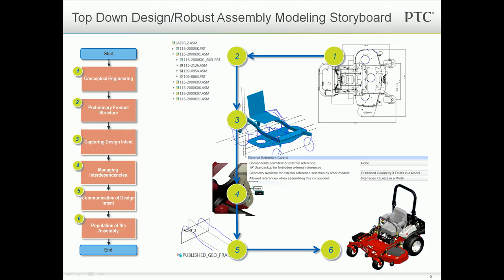During the product development process, an increase in top-down design methodology has been used in various industries. Creo Parametric provides a 6-stage top-down design solution for product assembly. Designers can use the Layout tool in Creo Parametric to plan the top-level requirements, define space allocation, and capture the key design intent. The second stage will create the initial product structure, which is the foundation of an efficient distribution of the design task.